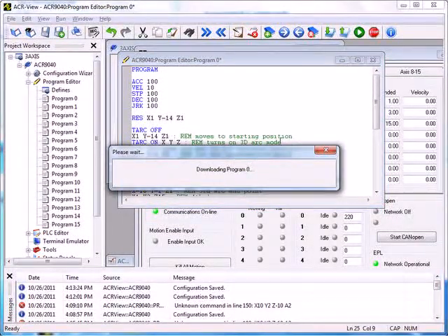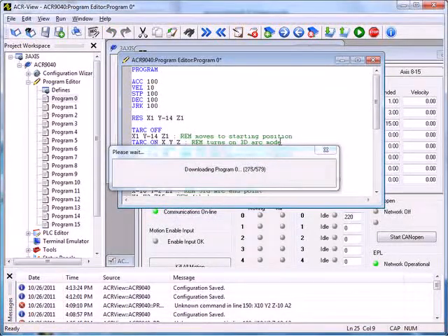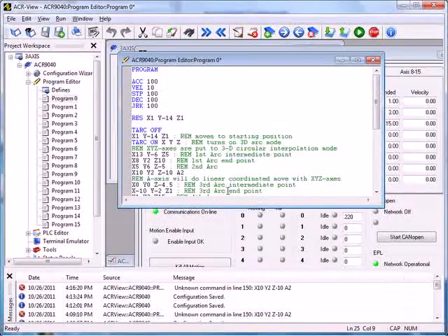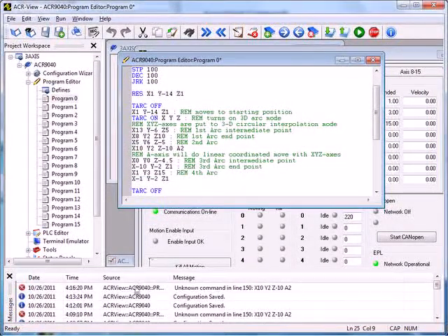You'll notice in the message box on the screen below that there's an unknown command in line 150. So if we take a look at x10, y2, z minus 10, a2, that a2 is actually a typo. We're going to have that fixed in a future version of the help guide. So I apologize for that, but I guess we could just delete that out.